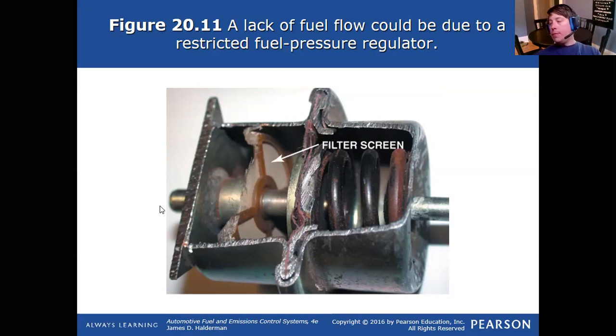It's kind of like if you change oil, you got a filter, and the oil filter O-ring stays on the engine. The new one has a filter. On the new filter, it has an O-ring as well. So you always have to double check that the old O-ring is removed. In this case, always double check that the old screen is out of the rail. Otherwise, you're not going to even be able to get the regulator on. That's what's going to happen. You're going to sit there and fight for 10 minutes until you finally look inside the rail and see the old screen filter, and you'll have to pull that out before you can move on. So anyway, I don't know where I'm going with that.